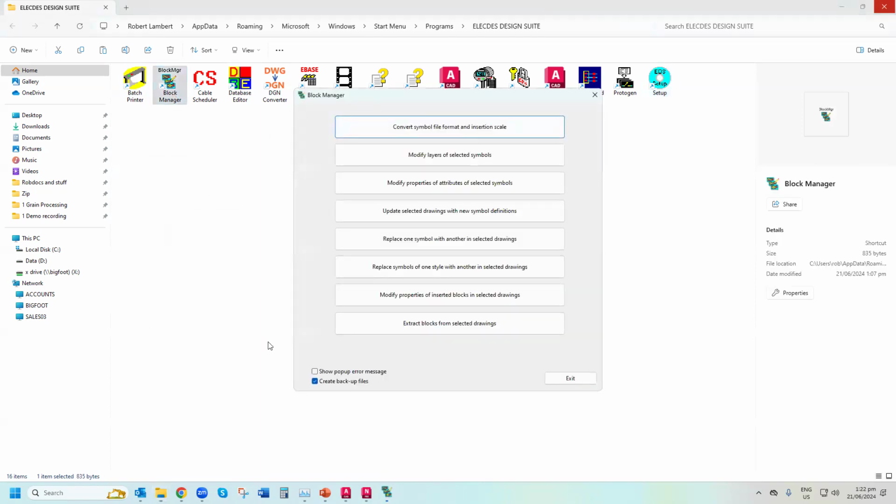The other thing is, in terms of flexibility, we had, for example, GE in UK doing work in Canada. They basically replaced all of the IEC symbols with IEEE symbols by clicking on that button there. If you've got customers that want to get more intelligent onto drawings, they might have some block symbols of their own, and they might not have the standard attributes that we need. So again, you can use this as a useful tool to change their block for a push button into our block for a push button, and then they'll get things like bill of materials and from-to wire and cable list and all that sort of thing as well. So that is important.